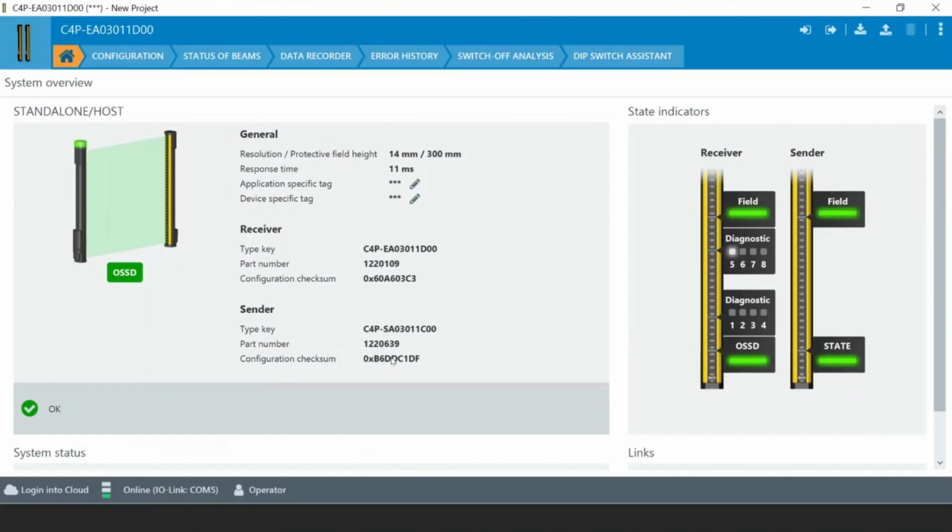curtains, because traditionally you would get a fault from a light curtain, a supervisor might come down and say, hey, go check the palletizing light curtain, it's not working right. Well, now, if you have all of your light curtains connected via IO-Link over your network, you don't get the safety functionality, but you do get this diagnostic functionality. And I really want to highlight that IO-Link is really powerful when it comes to safety as well. So when you connect to the device, you have a home screen.